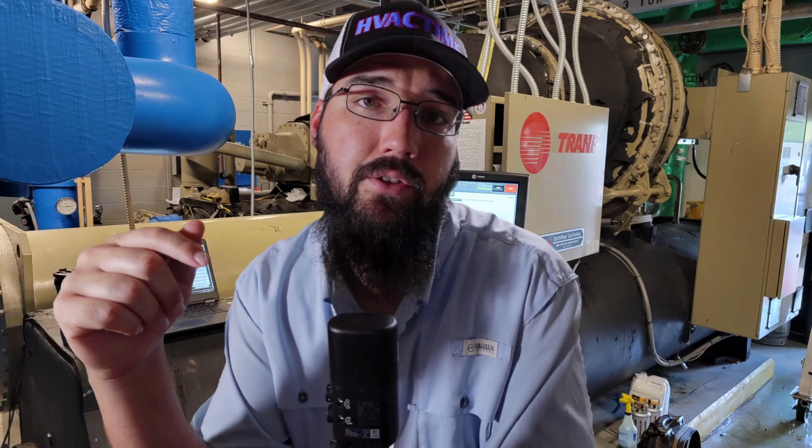that helps us pressure reduce that down and flash that liquid off, so it doesn't stay in the liquid form. But we were able to get the oil up at that point and get all that to return to the compressor, and then from there the compressor recycles it into the refrigerant stream and sends it through some oil separators, and it drains back out into the sump, and the cycle goes back around and around.